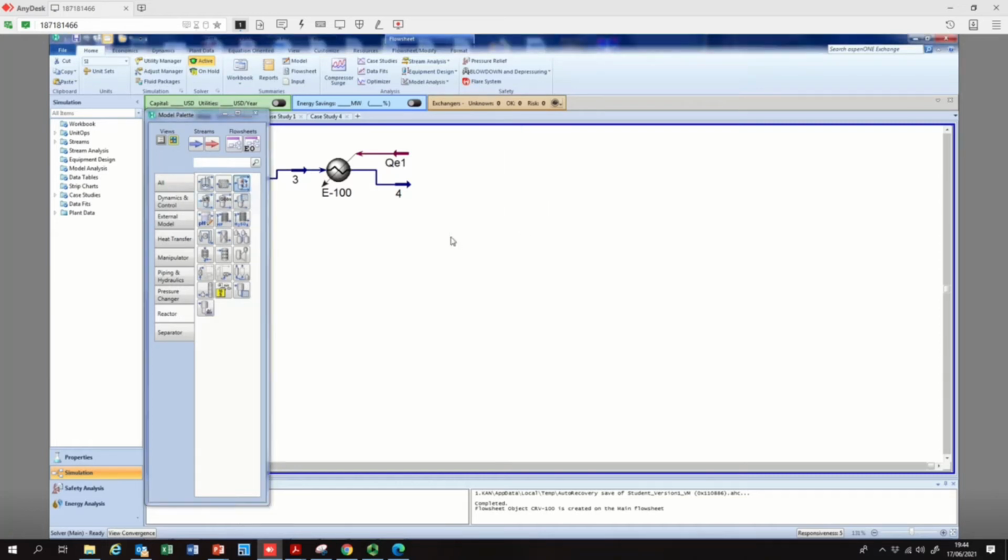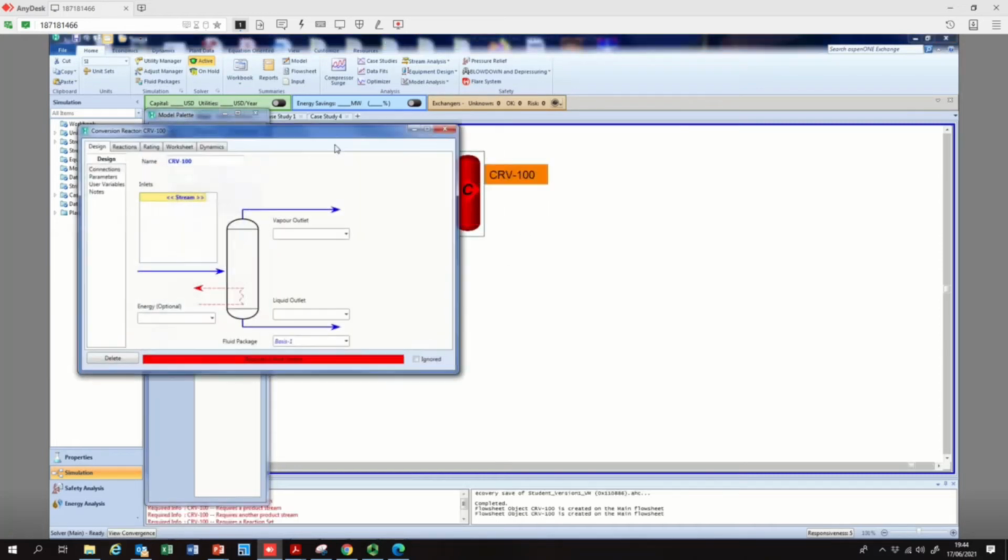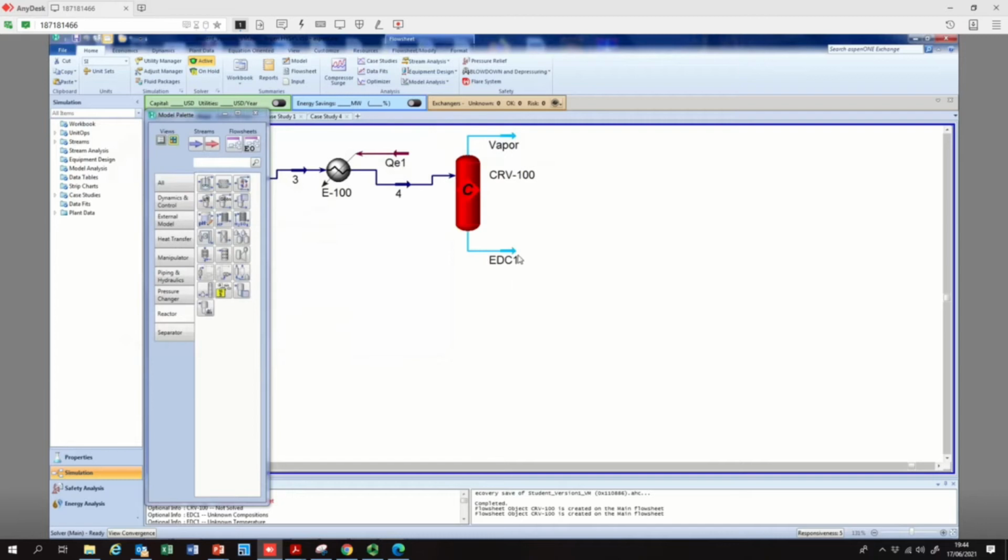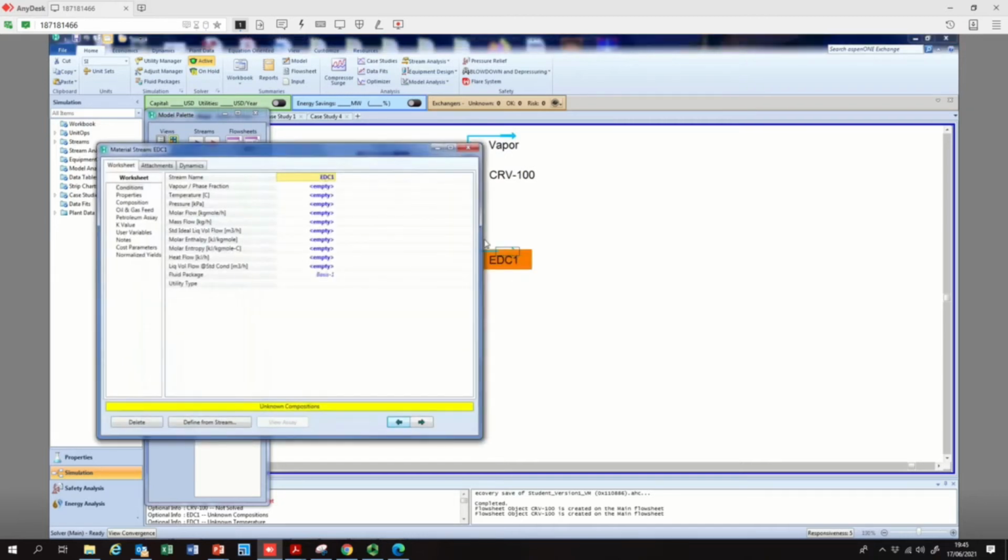Let's do this. Conversion reaction. Let's write product vapor. Let's say EDC1. Stream 4. And then let's close this and then click EDC.